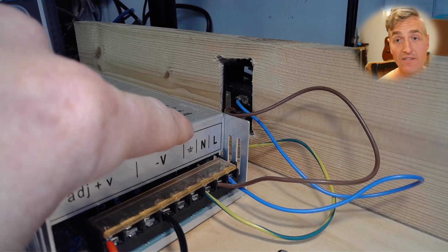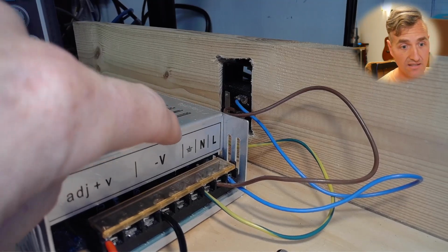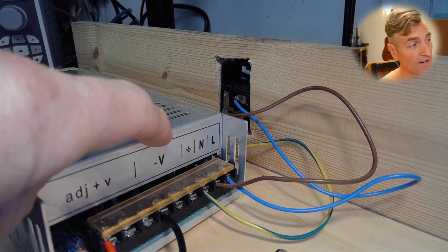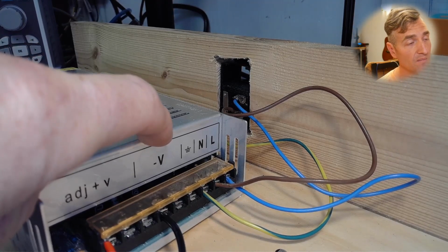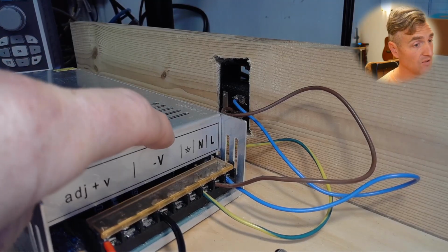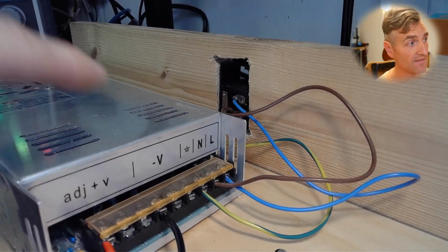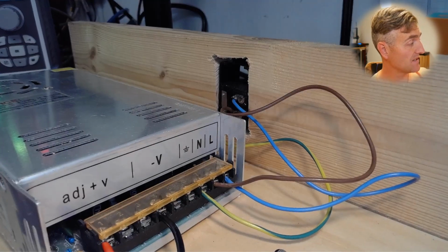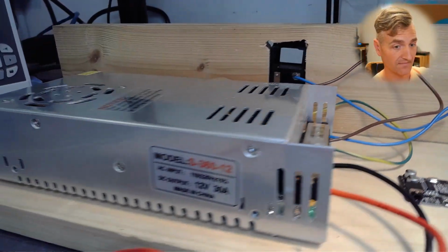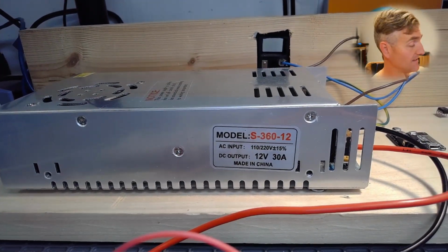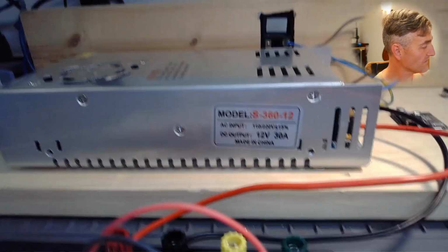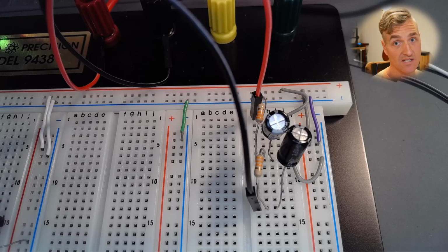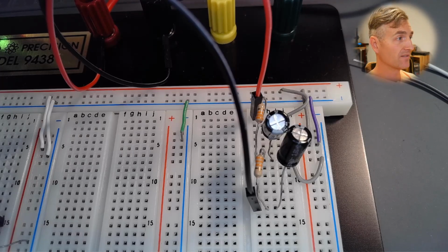So previously I had this ground lead tied to my negative because I wanted my supply to be referenced to ground. But to pull off this trick that I'm doing, which is splitting the supply in half, I have to pull that reference off because I can't raise the entire reference of the planet, but I can use some components here to split my supply in half, as long as my supply is not already referenced to ground.